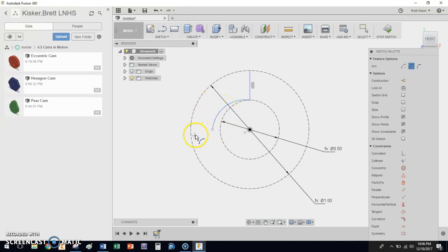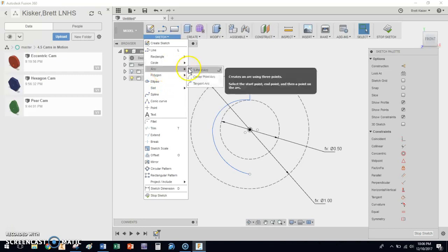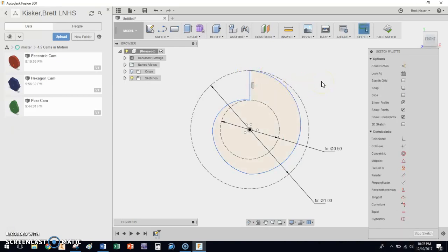I'm going to click. I'm going to do the same thing here: go to the center point without clicking and drag down. We're going to go about halfway between the two. I'm going to come over here, kind of place it, and right click. Then I'm going to make a third arc. Another 3-point arc here, up to the circle, drag out about 75% of the way, get the arc about right there, and then one more here to here, make it look decent. Click OK. That looks all right, doesn't it?